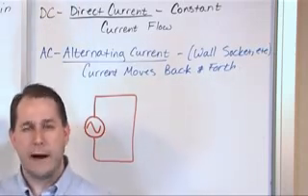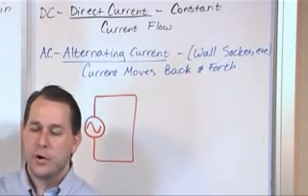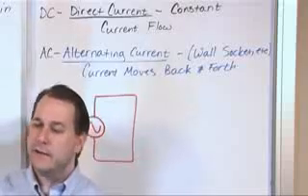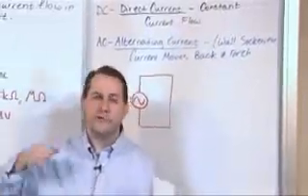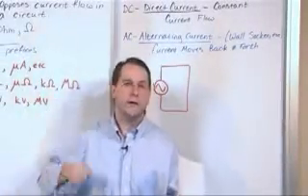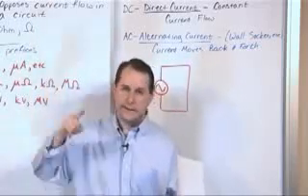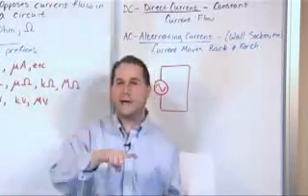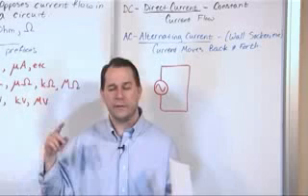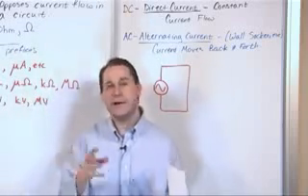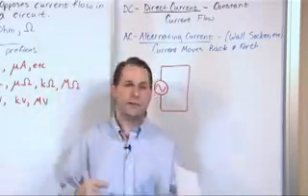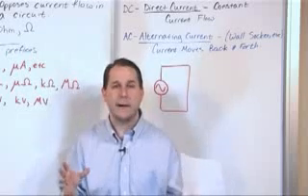Really, all of our power plants, whether they're gas or nuclear or coal or anything, all they do is generate a lot of heat, and that heat usually heats up steam, and that steam turns a generator. So all of our power plants, no matter how fancy, even the wind farms, are just turning a generator. Since they're moving like this, the current that's generated alternates back and forth. Every time we generate electricity, the only way we really know how, except for solar panels, we're doing it by rotating a wire inside of a magnetic field, which is what's inside of a generator. That rotation is a direct result of how we get alternating current, and that's really the reason why the power plants do that.